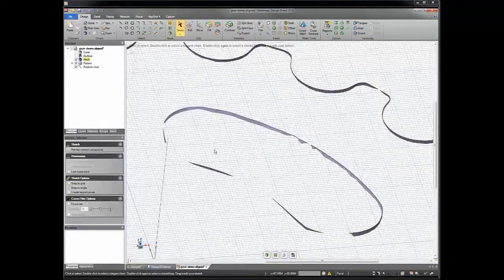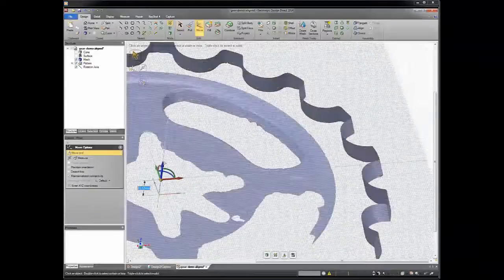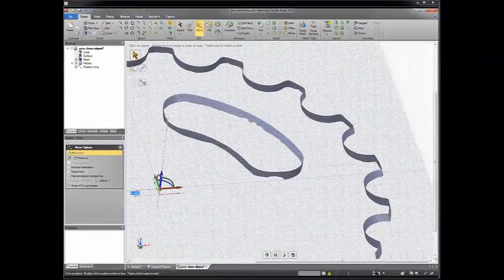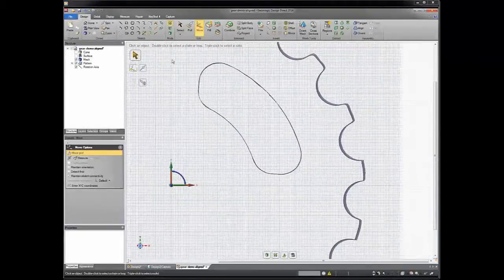When you go into sketch mode, as I alluded to before, it does a nice cross-section right through the mesh. I'm going to move it up just a little bit, and you can place this cut plane wherever you want. We're going to put it right here, and then we'll put it into a nice plan view, and we'll use the sketch tools.